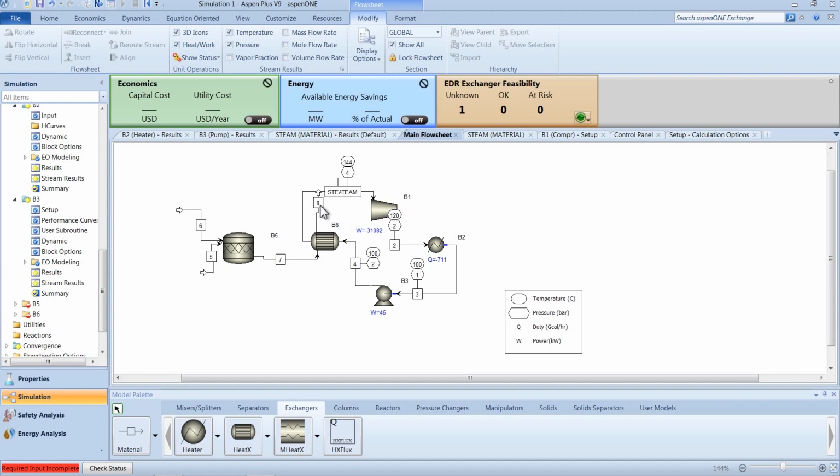Right. So 5, 6, 7, 8 is part of the combustion and flue. Flue gas will be composed of carbon dioxide, carbon monoxide, water, depending on your model. So that just usually goes out into the stack, or if you have heat recovery, goes through those.